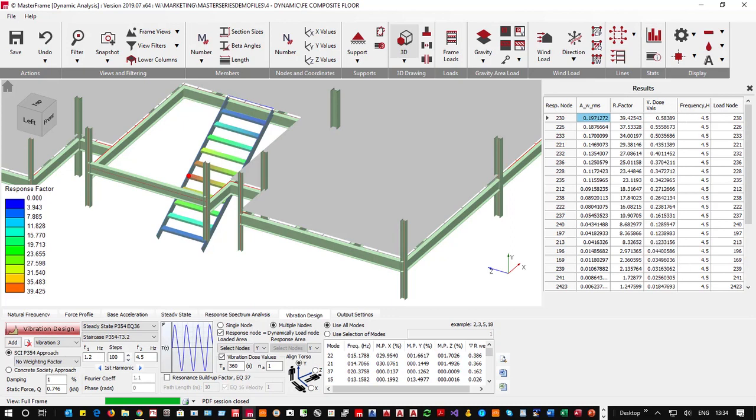But the next thing you want to do is to think about the fact that it's over a short distance. So we can say, let's go for a resonant build-up, and we're going to use it over a 5 meter length, not a 10 or 20 or 30 meter length. And if I now go and reanalyze for that value, we'll see the 0.56 has come down to 0.25.